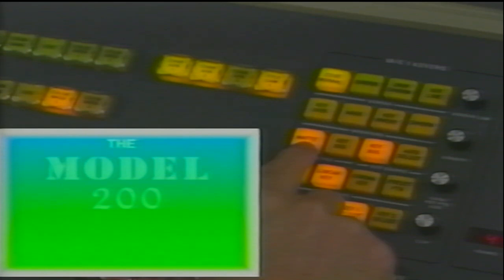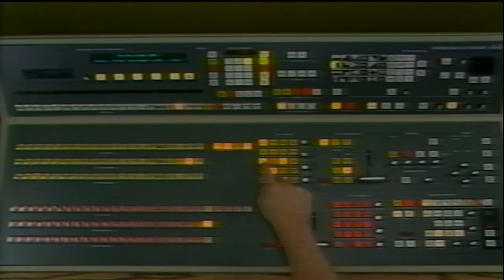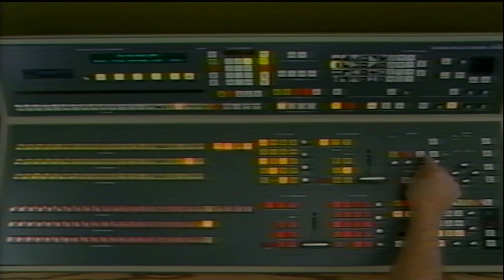Now, let's select a more practical example, such as character generators on the external inputs. As mentioned previously, we can accumulate these externals in any combination. By selecting the matte fill mode, we can replace the key bus signal and use our internally generated matte signal as the fill. This condition makes the graphic easier to read because of the greater color contrast between the fill and the background. When selecting the matte fill mode, we automatically delegated the matte control area to the matte generator for this keyer. This is done automatically, with no additional operator action needed.